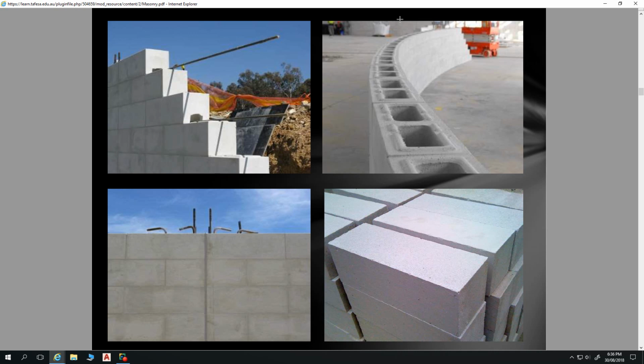With your concrete blocks, you can also include vertical reinforcing for core filling. So you run the reinforcing down inside these channels and fill those channels up with concrete to provide concrete structures throughout your wall. But you can also have longitudinal reinforcing as well with some concrete blocks. So they've got accommodation at the base here for running your longitudinal reinforcing in the walls.